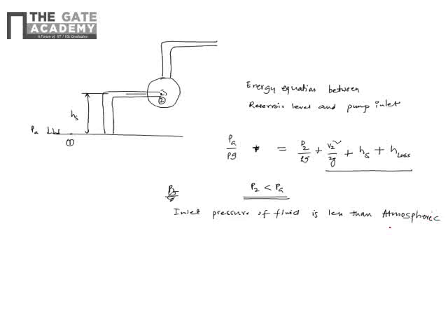But it shouldn't go below the saturation pressure at the operating temperature. Otherwise there is a chance of vapor formation.